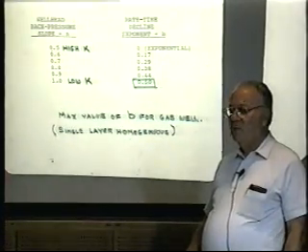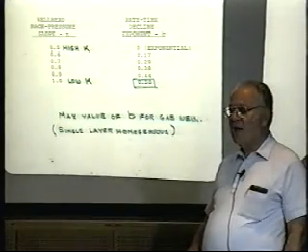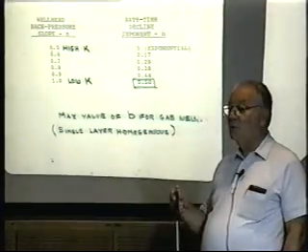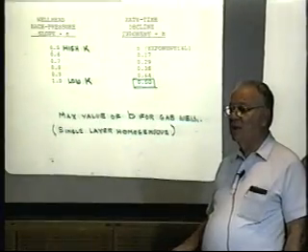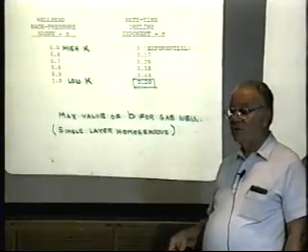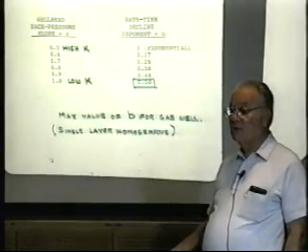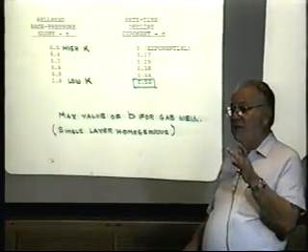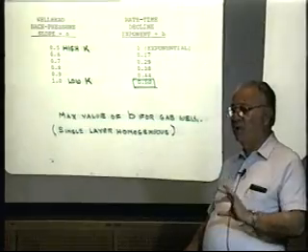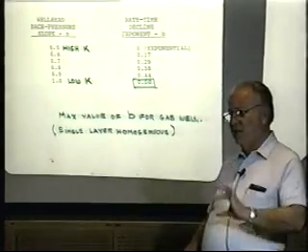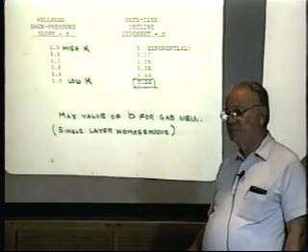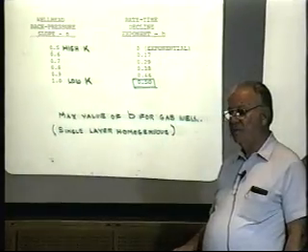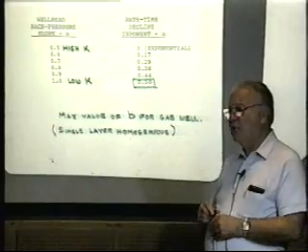And what you can do now to go backwards, what they're doing in Borger, I made this presentation out there a few years ago, and they're making money hand over fist with these ideas of going back to some of these old wells. You're cementing liners in there, perforating, stimulating by setting bridge plugs, and they're getting big increases in production. All right, how does it apply to Ekofisk?